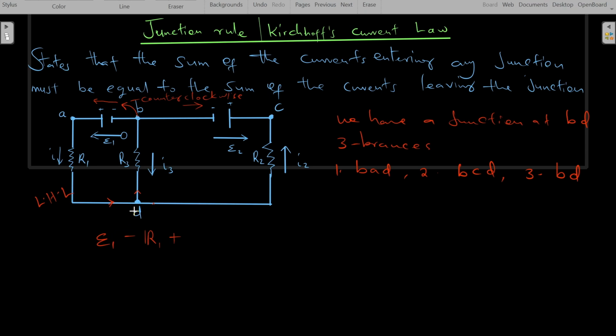This current is not the full current that's entering at this point, the reason is there's some current moving to this other side also. There's a junction at this point. This junction splits the current into two parts. So I'll say the total current should equal current 1 plus current 2.